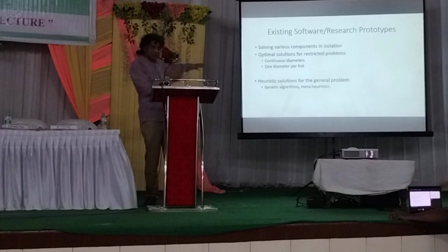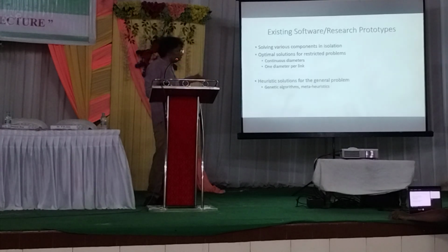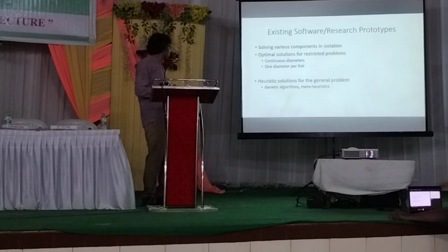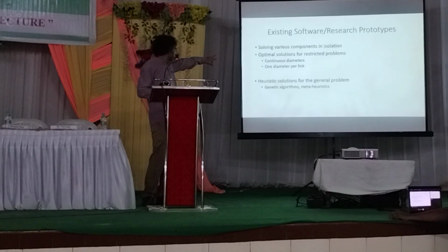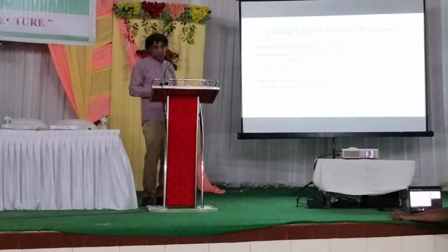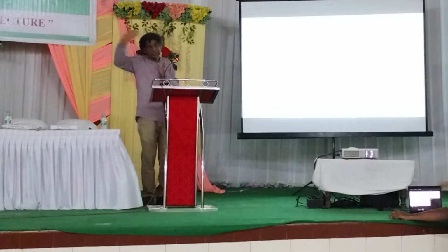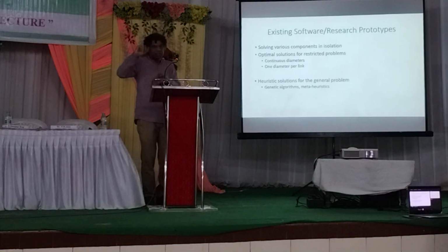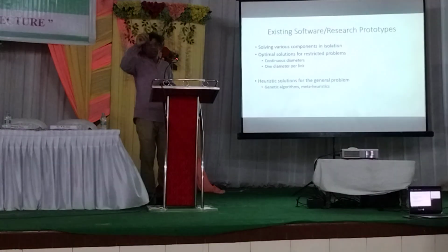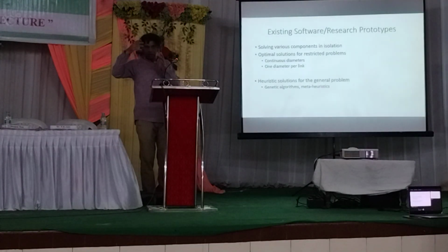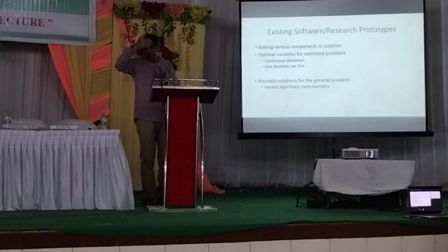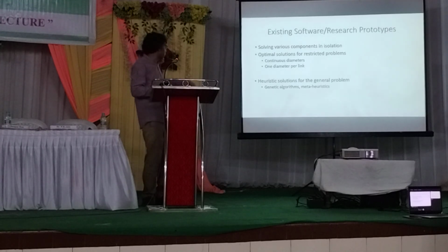So now what was the existing state of the art? Of course, till then also people were designing it either using Excel and EPANET or using certain software which made various assumptions. Some of them did not have this only 6 types of pipe. They will assume that I have a continuous diameter. Just mathematically find the best diameter. Say 3.72 meter, or 3.7 whatever inches. While it may just come in size 3 and size 4.